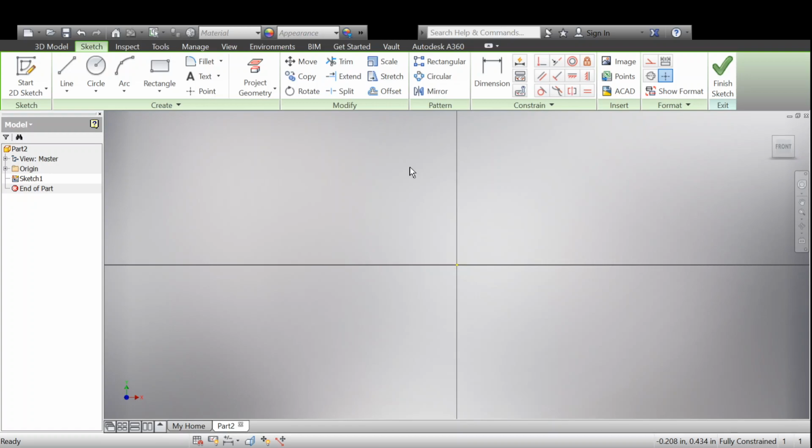So everybody take a look over here. First, does anybody not have this on their screen right now? And that's okay if you don't. Okay, so go up to View at the top. There's a little ribbon at the top that says View. Then go to User Interface. So go to View, click on View, and click right. Okay, then click User Interface, and then Browser bar.